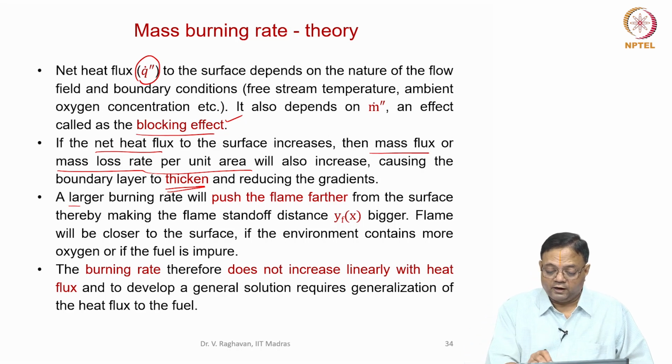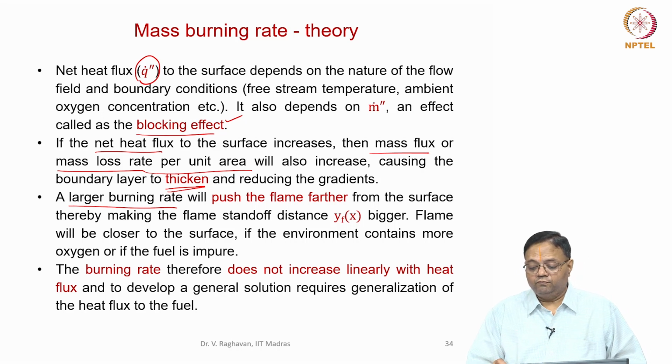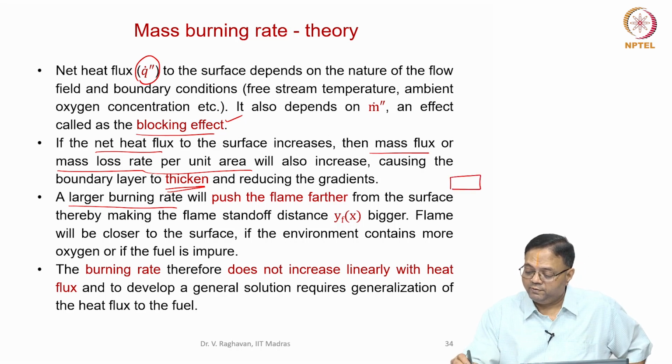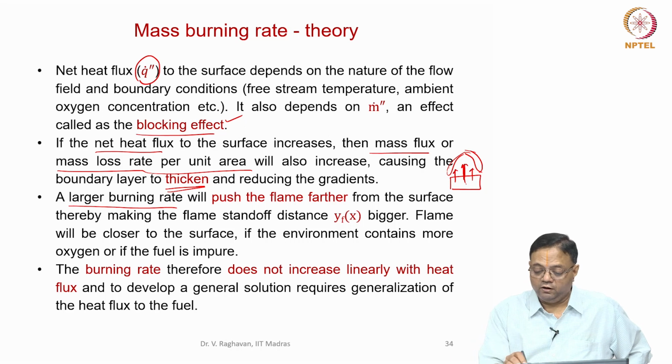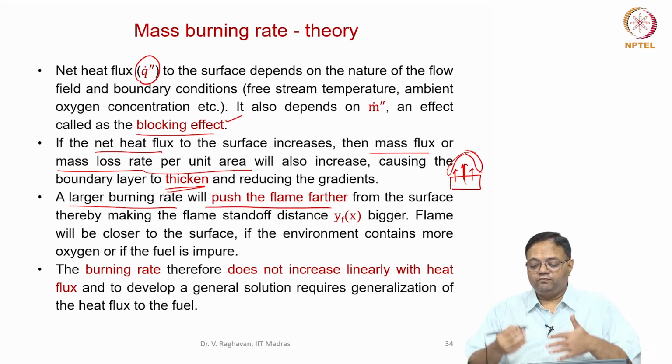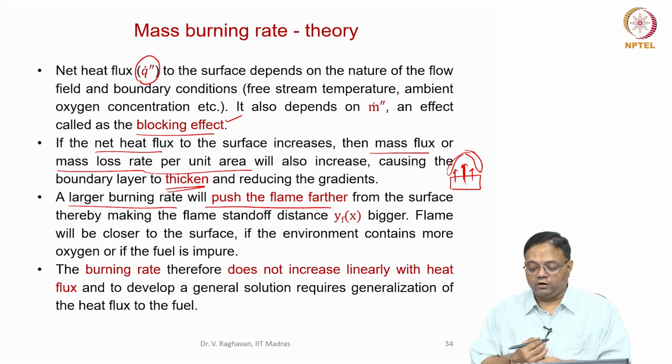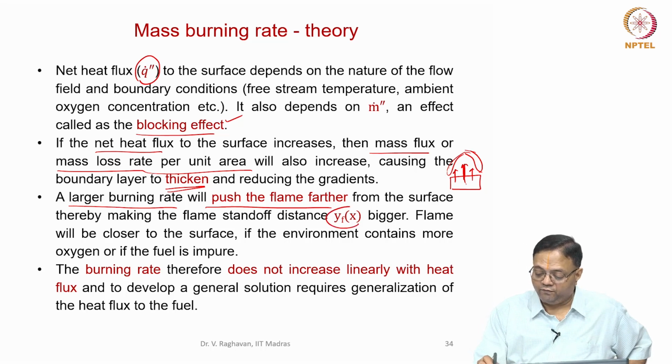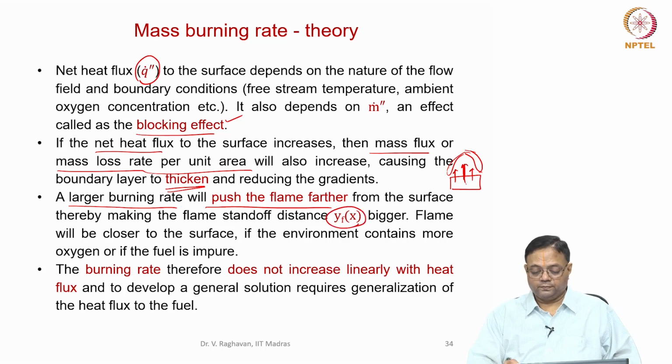When you have a large burning rate, a flame is formed over the surface. So now when the burning rate is large, then the flame standoff will increase. That is, the flame is said to be pushed farther away. So the flame standoff will increase.